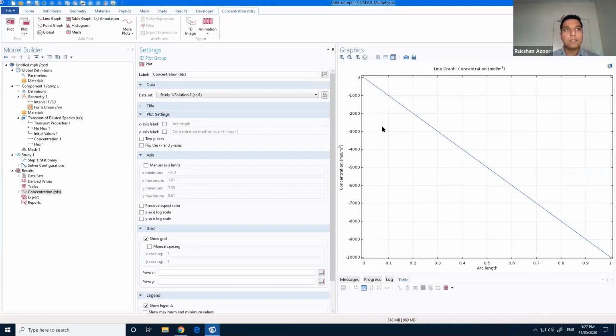Now, if we have something like a corrosion reaction or some other chemical reaction, we will not get any negative concentrations, because if there's no oxygen, simply there will not be any reaction. So in a physical system, if there's a chemical reaction, the reaction rate or the flux occurring due to that reaction will depend on the actual concentration. If there's no oxygen, there'll be no reaction, and therefore there'll be no flux. So we can do a small trick to make this a bit more realistic.